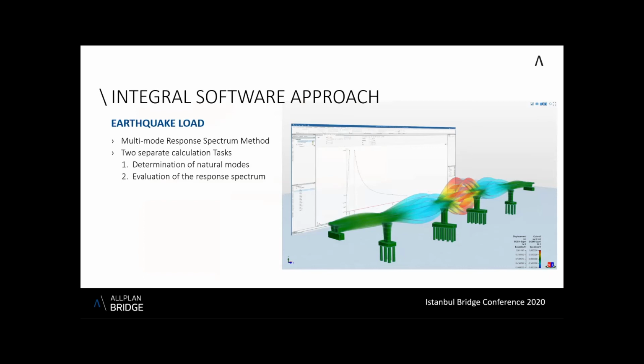This method is recommended in most modern design codes, and in our case, Eurocode 8 seismic design is already implemented. The effectivity of the method results from the fact that only a few natural modes need to be considered, due to high frequency vibrations being almost completely damped out.